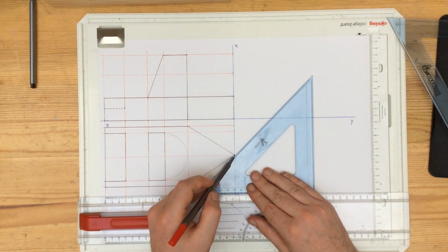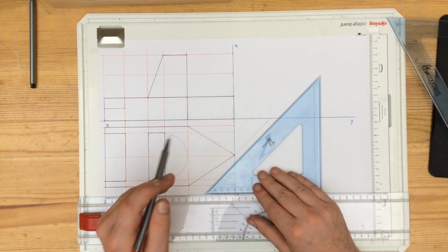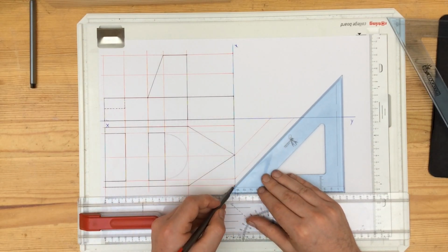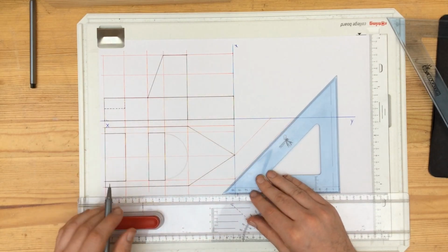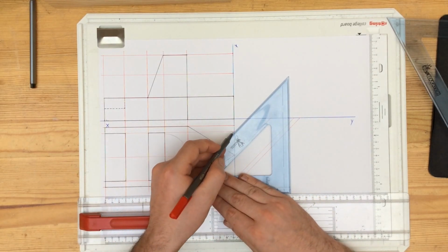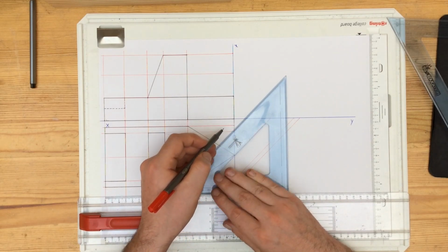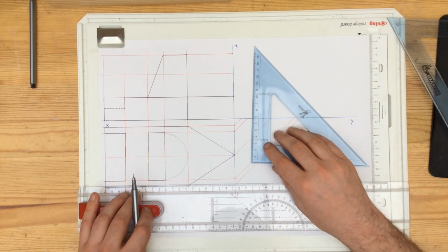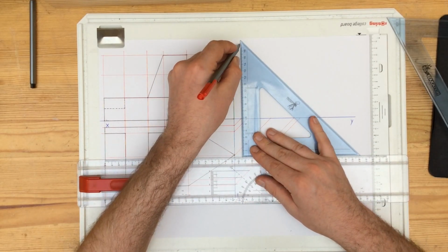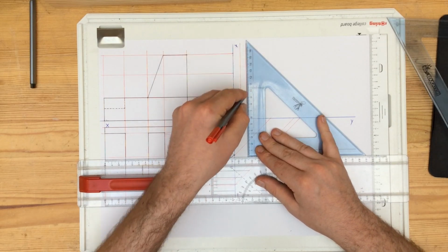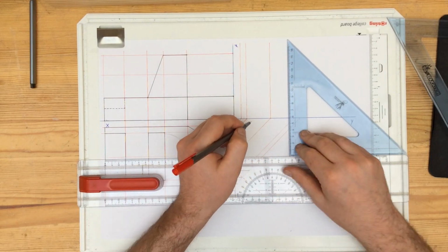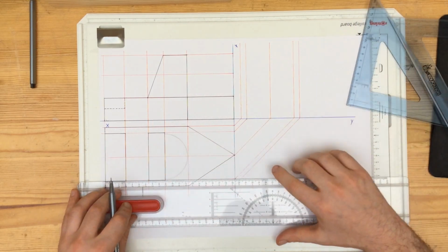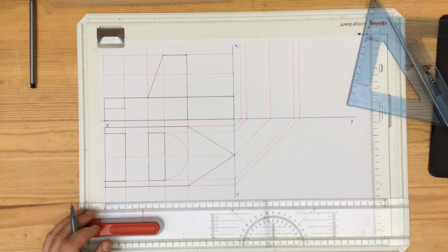My next step is to set up the end view. Every line must come off the XY line at 45 degrees. Any lines from the plan that don't hit the XY line must be brought to the XY line before being brought up at 45 degrees. Once they hit the XY line coming up at 45 degrees, they are drawn straight up. Again, all these lines that can be seen in red are construction.